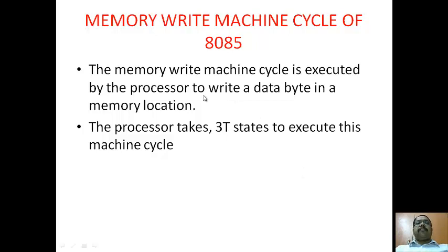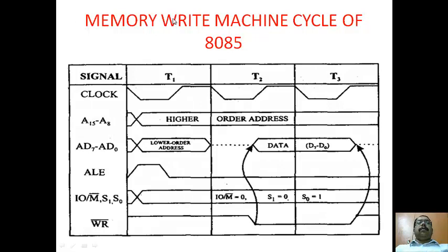That type of operation is called the memory write machine cycle. In memory write, again on the first T state, both addresses are brought in. Once both addresses are obtained, ALE is brought to 0 and the lower lines again become data lines. Now please listen, till this instruction we were seeing only read, and this is write. So the write signal will be brought.